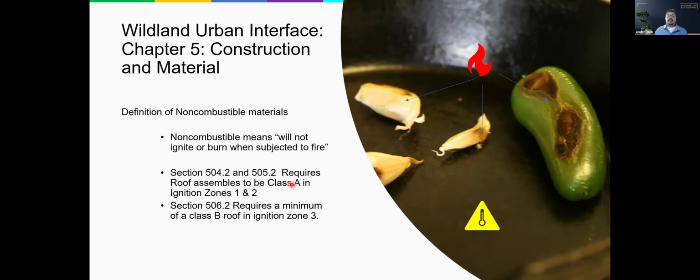And it's important to remember that it's a Class A roof in its totality here versus a Class B roof, right? There are many metal roofs, for instance, that are considered Class B because they're going to transmit that heat right into their framing members because of thermal conductance.